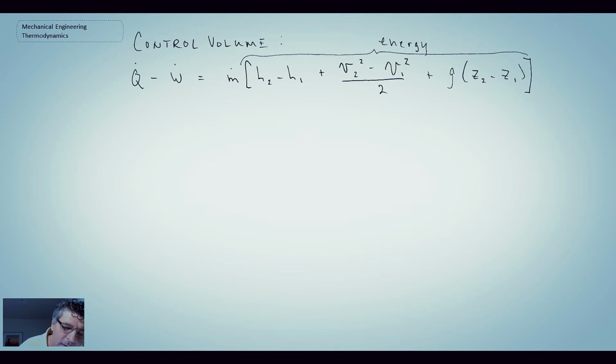And so we've come up with expressions for the exergy associated with those different energy types. So let's write out the exergy. And for this, we're going to give it the symbol psi. So we have exergy associated with the enthalpy, plus exergy associated with kinetic energy, plus exergy associated with potential. Plugging in the values,